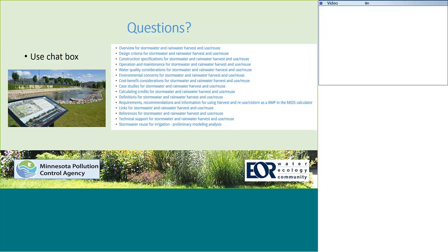Should a general amount of 1 inch be used for irrigation calculations, or should irrigation demand be based entirely on potential evapotranspiration? I think what we're saying is you can do both. You could use 1 inch, but if you use 1 inch, you're probably going to lose some volume, because in the summer months, PET is greater than that. If you restrict it to 1 inch, I think you're going to lose some volume. And then you can also consider some infiltration into the soils and being stored there. That might trickle down into some shallow groundwater or be used later.